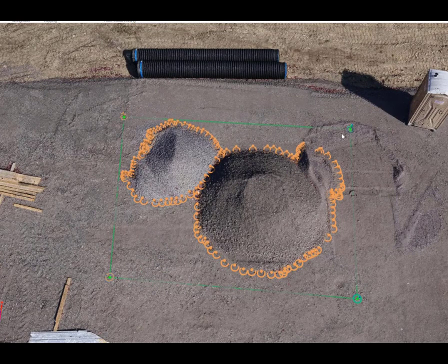So we set 4 hubs around the stockpiles, RTN, GNSS positions, process the imagery with the GCPs, and that was a big class in the remote sensing, 20 students. Each student went in and digitized and computed the volume of the small pile, the large pile, and then the exterior of both piles together, and made a comparison to see how the sum of the small and large pile volumes compared with the composite total volume.